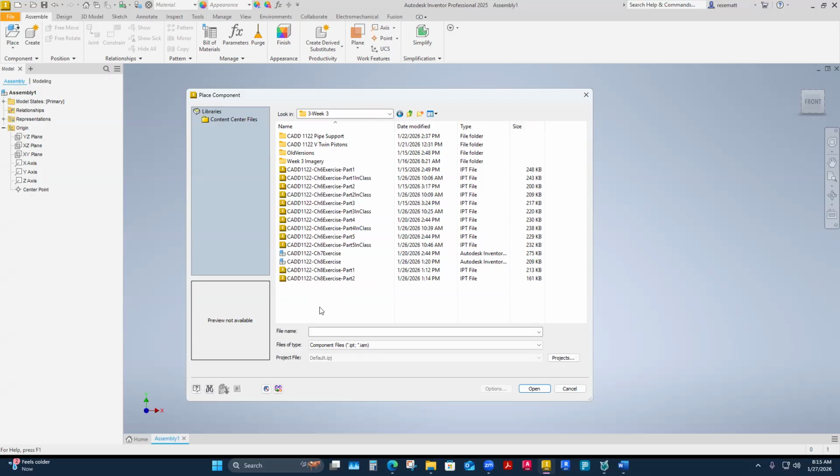But anyway, you have to get pretty good at organizing files, because if you move those files, you complicate things because of the communication between parts, assemblies, and drawings. If you start moving stuff around within your file structure, you usually have to go re-find it. You'll get a prompt that you've got an error, something is missing, cannot find where that file used to be. So if you have a drawing with a part and you move the file, it's going to give you some errors. You're going to have to relocate it and realign it. Pre-planning your folder structure helps prevent some of those problems. We should have some of that blow up on us, and I'll try to make some of that happen so we can work through how to fix it.